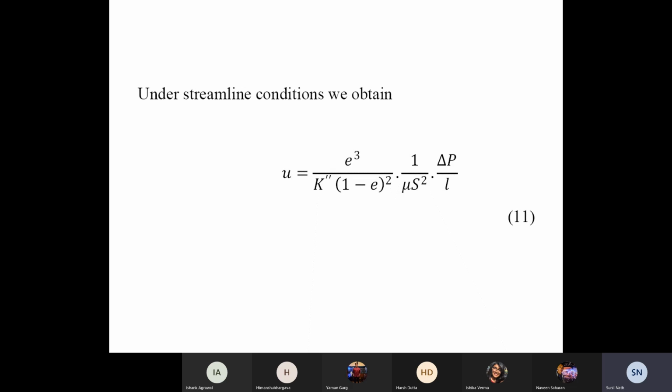It's inversely proportional to fluid viscosity, which is exactly what Darcy found in his Darcy's law statement and by his experiments, which I outlined to you in the first class. It scales as the square of the specific surface area in meters squared per meter cube for the bed. It's inversely proportional to the length, again the same Darcy's dependence, and it's directly proportional to the pressure drop. Okay.